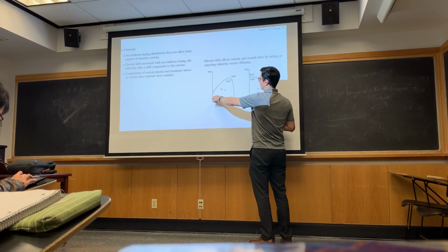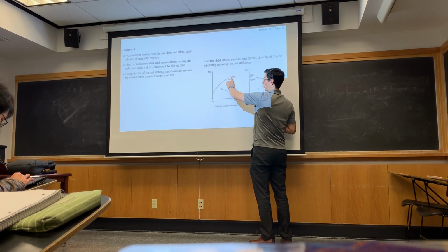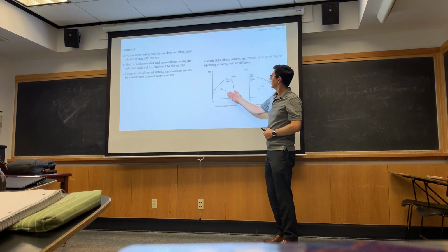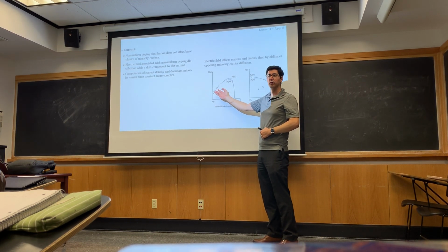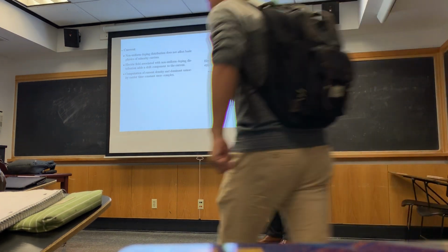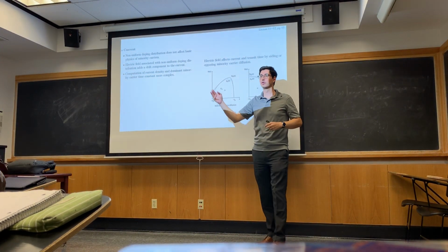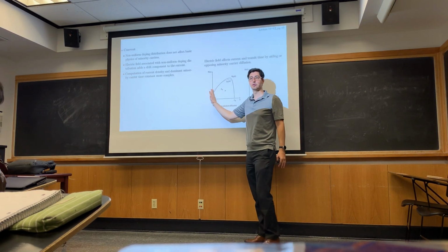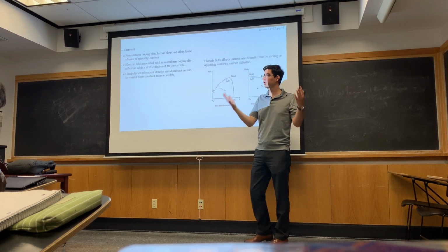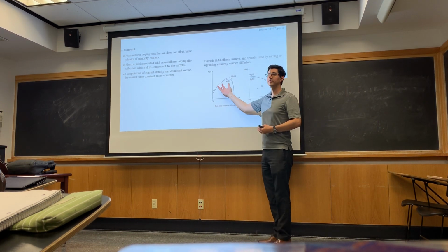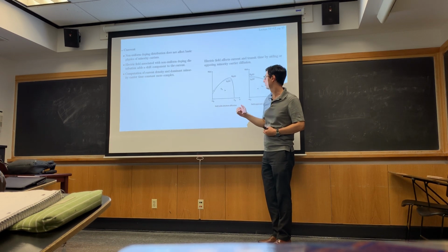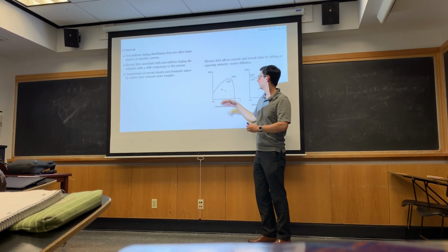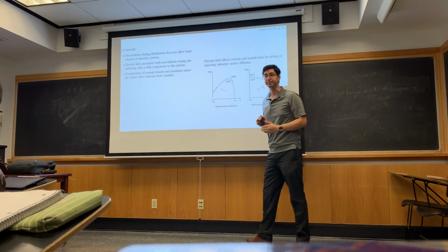But what we're trying to show here is if the NA concentration was upward sloping like this, and remember the junction's over here, well, due to non-uniform doping, we're going to have diffusion of carriers, right? And so carriers are going to diffuse from where to where? From high concentration to low concentration. So that's what you see. They diffuse, non-uniform doping, that creates an electric field. What direction is this electric field in? Well, we have a net negative charge here, a net positive charge here. That creates an electric field this way.